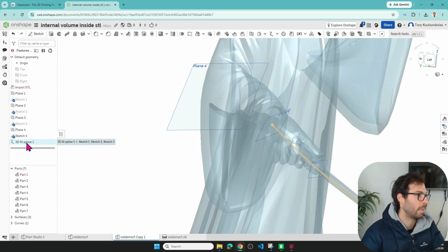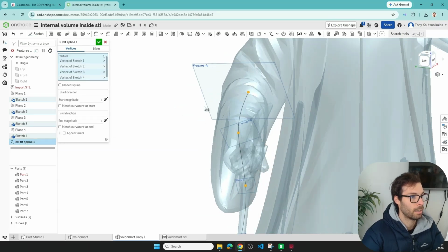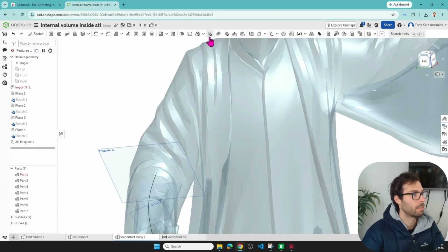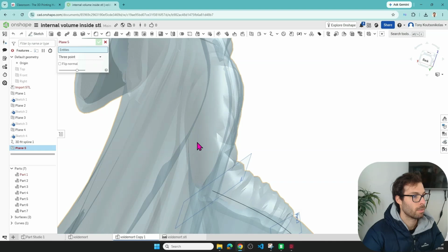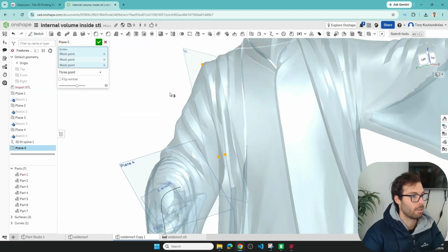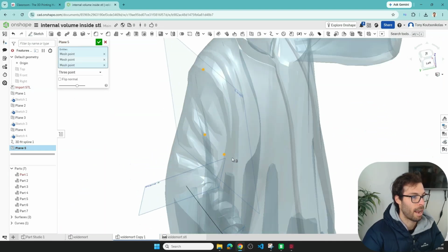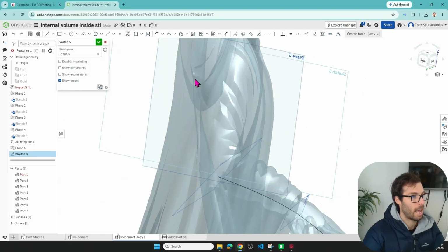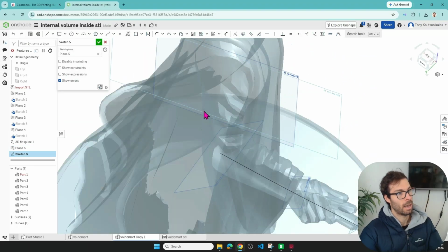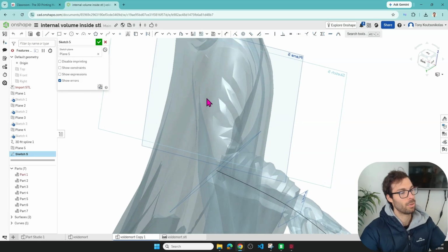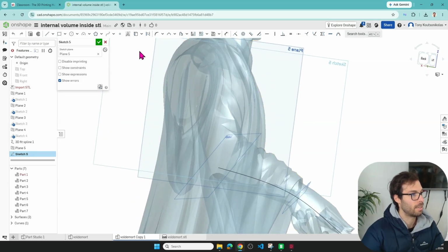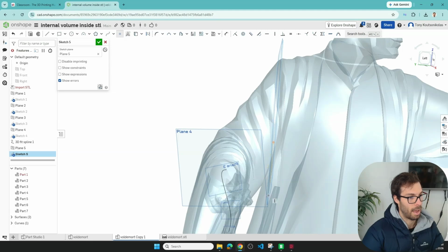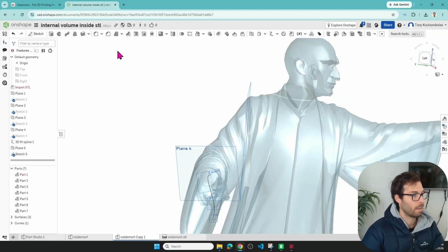And I can put my 3D spline there and update it. There we go. Now it probably has to come across a little bit more towards the middle. I've clicked on the shoulder here, and you can see now I'm gonna take that right angle. It's gonna turn around. So hit sketch on this. And now I'm looking at it from this side because I want that curve to come towards that plane. So I've got to look at it on this angle, and I might even make it come up a little bit. So I can come over that kind of armpit there, and then click OK.